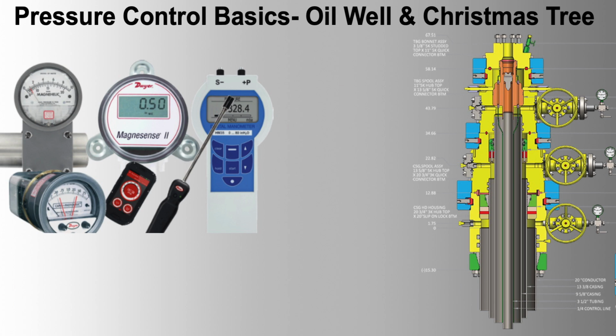Problem: overpressure events leading to equipment damage and safety risks. Solution: implement automated control systems that can quickly adjust choke valves or alter flow rates to maintain safe pressure levels. Use predictive analytics to anticipate pressure surges and take preemptive actions.